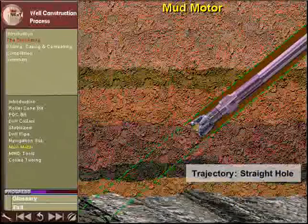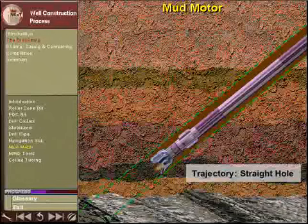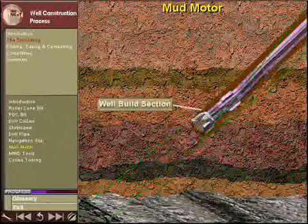In directional drilling, the straight hole portion of the deviated well is drilled just as in conventional drilling. The entire drill string is rotated. The tilt angle of the navigation sub is very small, and therefore the eccentricity of the center of the bit is small. Thus, this assembly can be used for straight hole drilling.